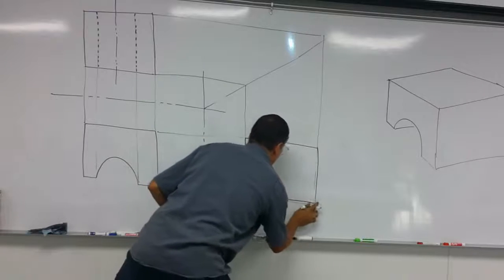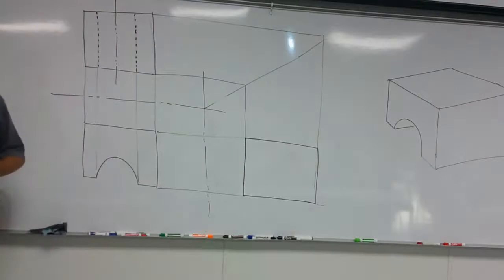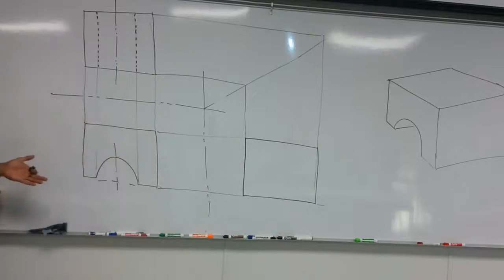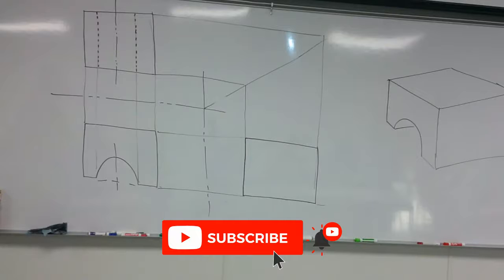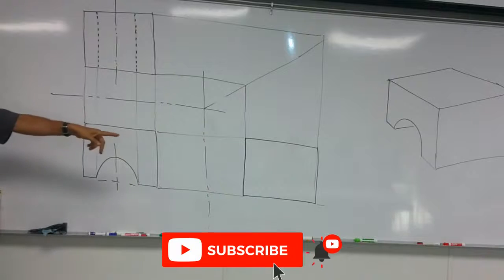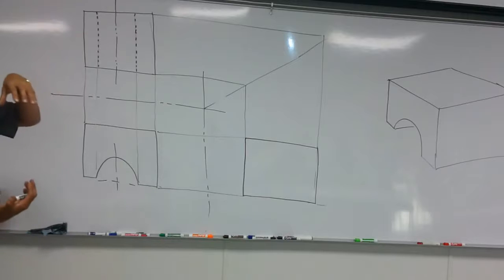And what about this section in the lateral? Invisible. On the top view, how do we know that it's not just a hole in the middle? No, because in front you have another center line indicating that it is half. For that reason, you need another view. In some cases, you say no. This is a good question. It's more representative for my picture, the lateral of this side, not that one. Or the bottom view, not the top, because you have a drill in the bottom. That depends.